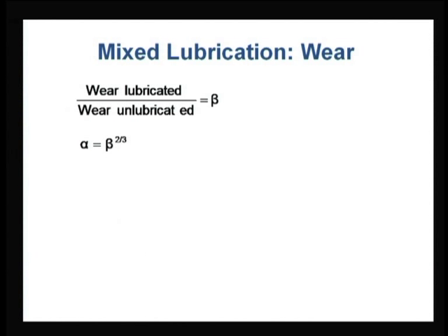In the previous slide, we showed the friction calculation and how we can go ahead with this kind of calculation. That is another way to treat this and get comparative results. But we are talking about wear under lubrication, where a lubricant is available and wear is still happening. That will cause lesser wear compared to unlubricated, because more and more rolling action will occur, and in that situation abrasion and wear will decrease.